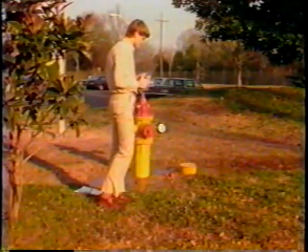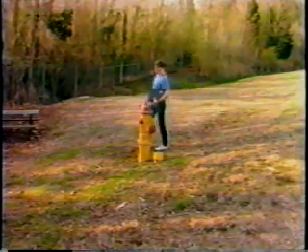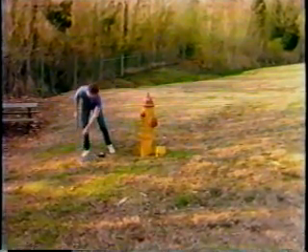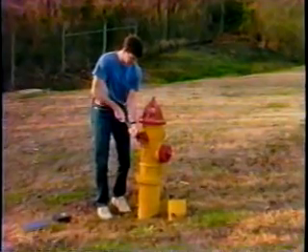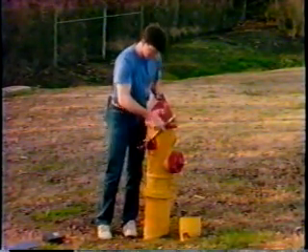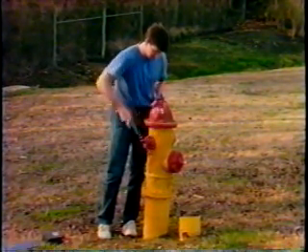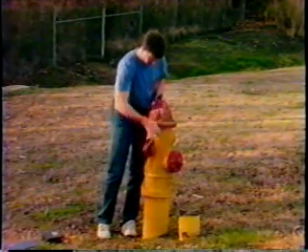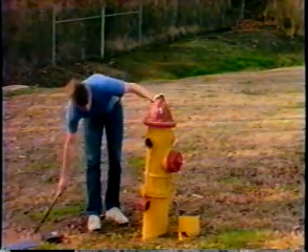Now let's see what's going on at the flow hydrant. Upon arriving at the flow hydrant, the individual who's going to be conducting that part of the test first assesses the area and selects the outlet to open that will cause the least amount of damage due to flooding and erosion. He then removes the cap from the hydrant outlet and bleeds any debris or sediment out of the hydrant lateral and barrel.